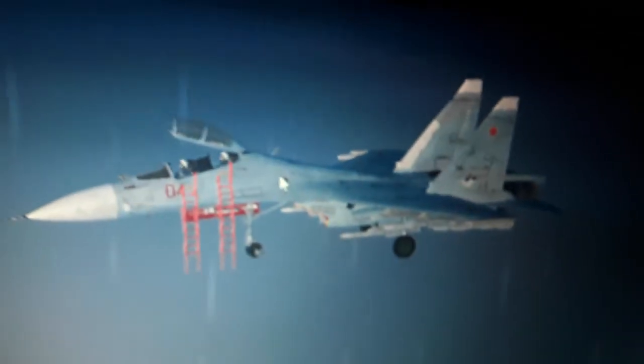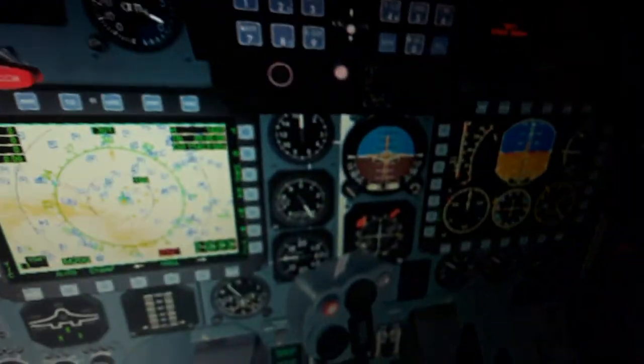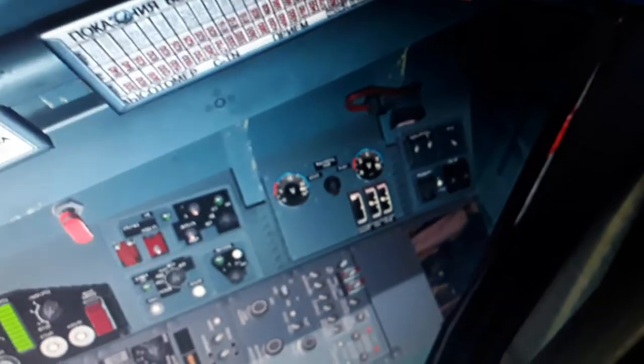So we'll come here again and close this position. Close the canopy and make an engine start demonstration. Okay, use this switch to close the canopy and open it. So here it is. Close the canopy. This is for ejecting the seat, but before doing so you have to arm this switch over here,